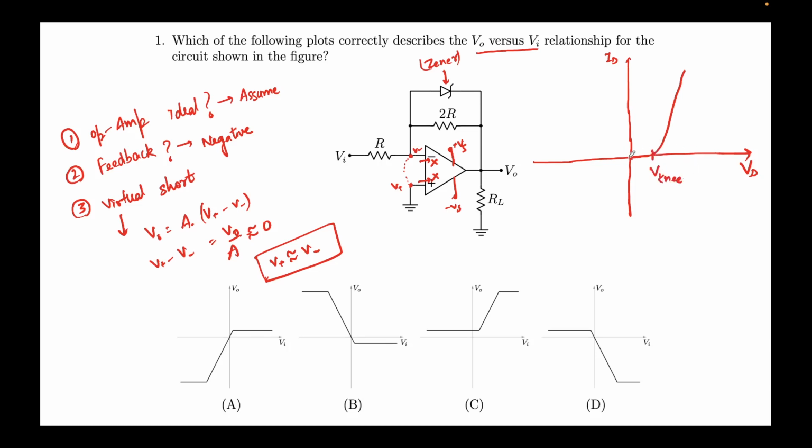In the opposite direction, we know that there is some leakage current which we see, and suddenly the current increases and the device is said to have broken down, right? This is what we call the breakdown voltage, and in a Zener diode this is also known as V_Z. Usually there are two kinds of breakdown, the Zener breakdown and the avalanche breakdown. Avalanche breakdown devices sometimes break destructively, meaning they cannot be reused in the forward direction. The beauty of the Zener diode is that it can be used in this breakdown condition also.